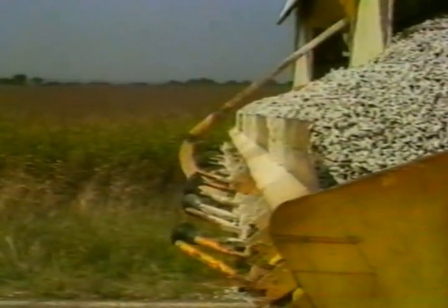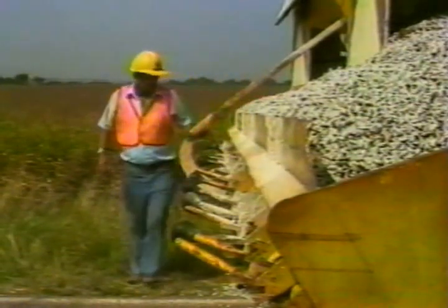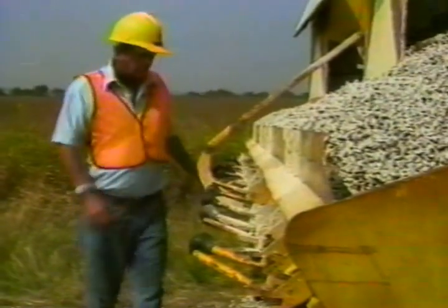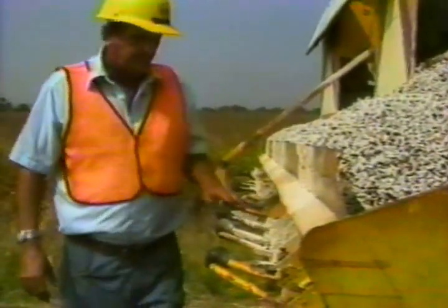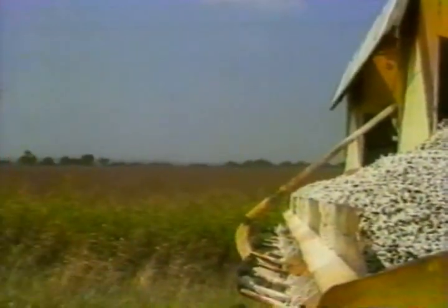The chip spreader, like all the other equipment, should be checked each morning for operational readiness and safety. But even then, problems can still occur. If one of the gates jams in a closed position, it shuts off a small portion of the chip fall, as is clearly shown by the opening in the chip fall and a corresponding strip of exposed binder on the surface.